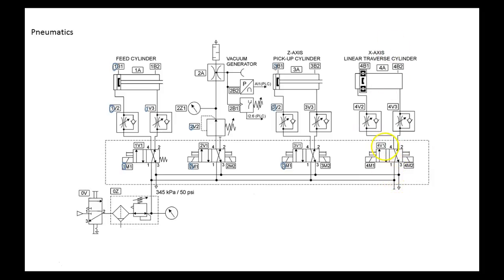So 2, and we start from the control valve up. So notice this is labeled what? 1. All these are labeled 2. That's the second thing we see. Your load is going to be the very highest number of the circuit. Does this make sense? Everybody okay? So here we have 4 circuits, and that's what this shows. So we have, actually we got 5. We have the power circuit down here, and notice it starts off with 0. Okay, because it's not an actuator circuit.